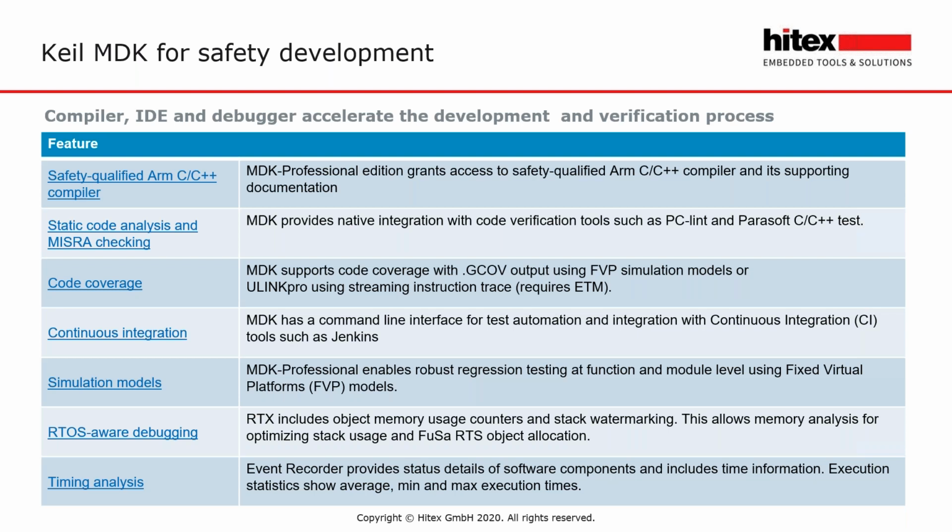Within the debugger of the Microvision, we have a lot of RTOS awareness. There's a component viewer that will show you a very deep view of the state of the operating system. And as I mentioned, the event recorder will put out a lot of instrumentation information about the operation of the RTOS as well.